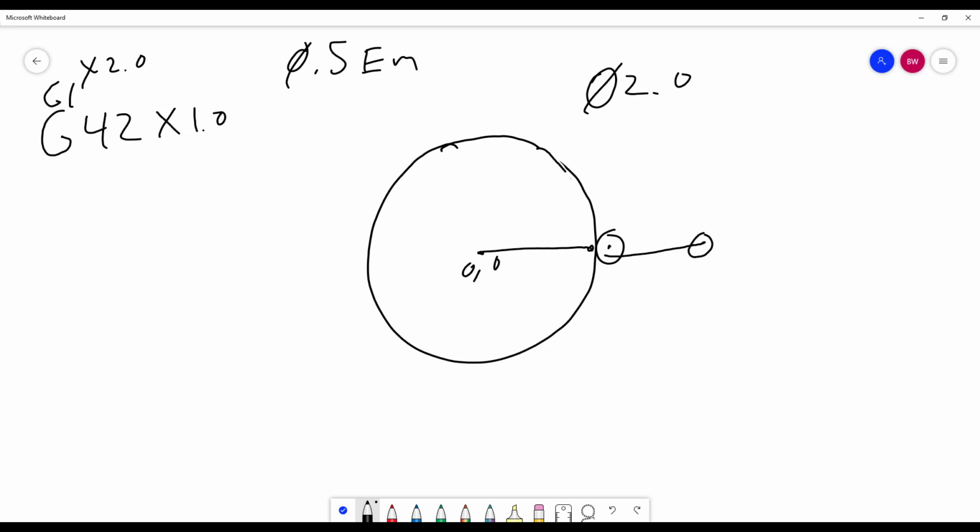Now, I prefer to have a G1 code modal before you turn comp on. I do not like to put the G1 on the same line. So you could just put a G1 before it with no move. Usually you're going to have the G1 on the Z move before you're here with some sort of feed rate. You can put a feed rate, if this is D1 and F of 10, you could do that. It's up to you. But let's just focus on getting the comp on.